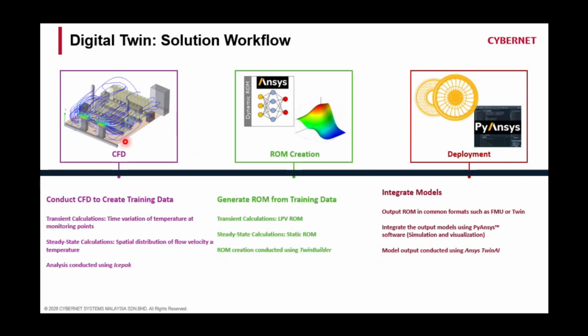Okay, so first things first, we need to create a ROM. But before that, because this is the digital twin for a data center, in order to assess the temperature and velocity flow field of your data center, basically the airflow performance, we are going to have to have the data first, right? So to do that, we are relying on CFD. For those of you who don't know, CFD means computational fluid dynamics. The CFD simulations solve all these things, so you get to know the temperature and the airflow inside the data center.